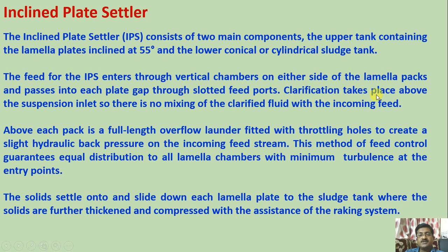Clarification takes place above the suspension inlet, so there is no mixing of the clarified fluid with the incoming feed. Above each pack is a full length overflow launder fitted with throttling holes to create a slight hydraulic back pressure on the incoming feed stream. This method of feed control guarantees equal distribution to the lamella chambers with minimum turbulence at the entry points. So uniformity is maintained there.